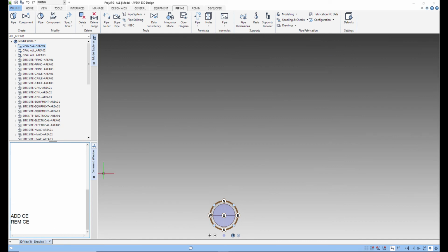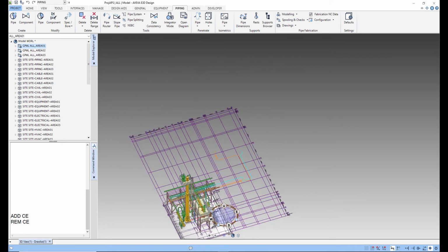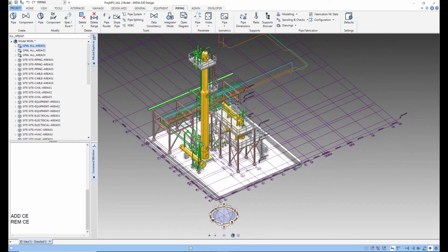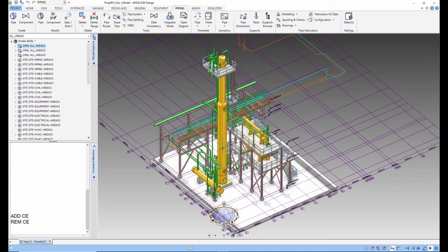So this is how you can add your database element into your drawing canvas, and you can start working on it. This is not like adding and deleting. This is just for removing from the drawing canvas. Your items will be there in the database, so no need to worry until and unless you use the delete command. I am covering very basic things because everybody can take advantage of this video tutorial. I am not targeting only an audience who is using E3D and wants to enhance their productivity. I am targeting new guys who have just started using E3D, or are just planning to take training.